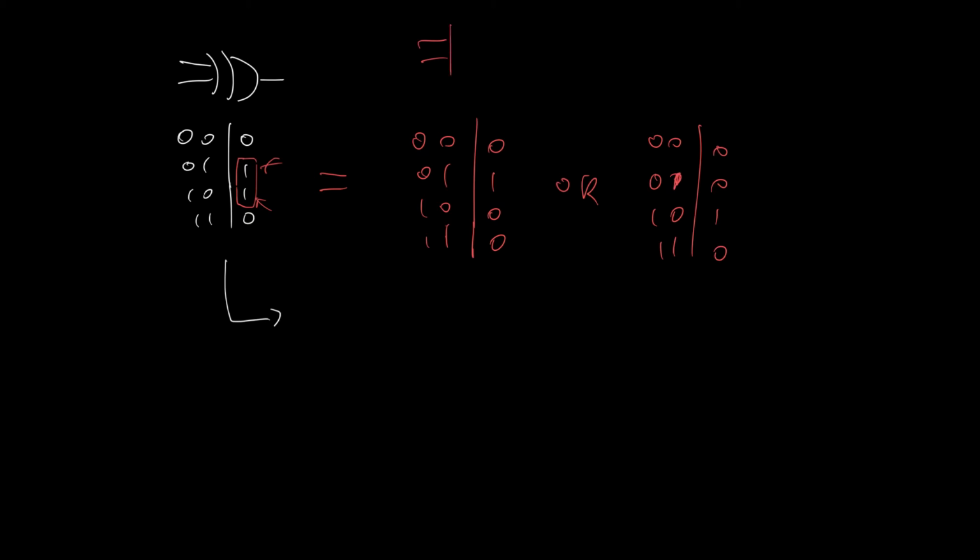Let's assume 0, 1 goes in. I'm not writing it down because we can do this in our heads once we're used to it. So if 0, 1 goes in, then I've got 0, 1 going into this gate, and I have 0, 1 going into this gate. If 0, 1 goes into this gate, then according to this, I have a 1 coming out. If a 1 comes out, then at an OR gate, as soon as any of the inputs is a 1, we know the output is a 1. Therefore, I immediately know that in this case I have a 1 coming out.